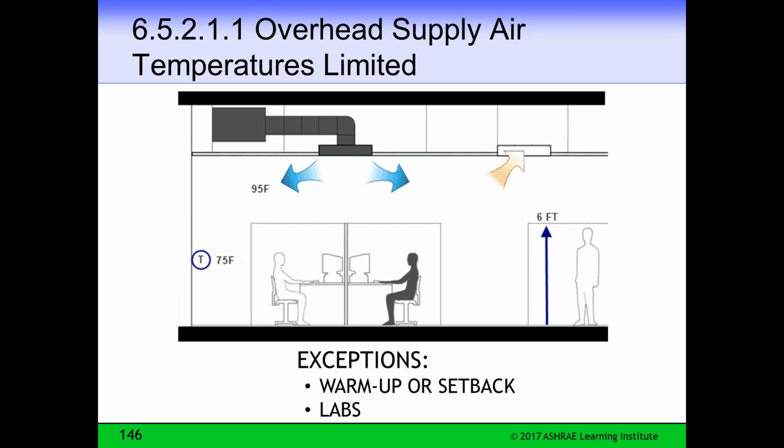Now, ASHRAE 62 says if you don't want to do that, you can put in 20% more outside air. Of course, in certain climate zones, that's a problem, and so it causes trouble. So what we thought was that at least by putting in this box that was sped back up, you would have some chance of getting more throw towards the ground of the hot air that you were producing by the box. So that's one of the ideas we were working on, to try to help with that situation. Also, again, it just saves a little bit of energy.